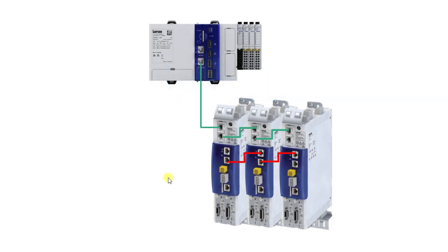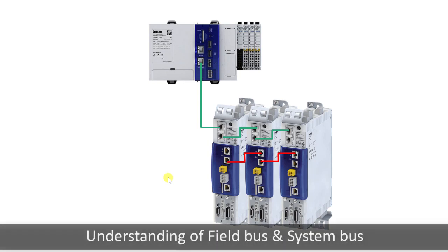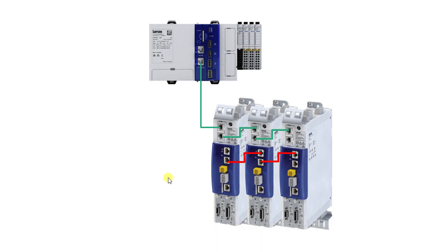This tutorial shows how to set up electrical shaft application in i950 using System Bus, and run the axis from controller using Fieldbus. i950 drives have two types of EtherCAT connection possibilities. One is onboard EtherCAT communication interface and the other one is Fieldbus EtherCAT interface.